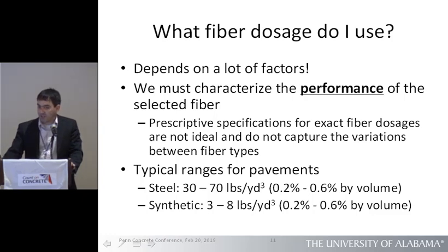So we want to characterize the actual performance of the fiber and not just always say, okay, we're always going to add 4 pounds per cubic yard and call it good every single time. We want to look at how the specific fiber that we're choosing to use performs in our mixture.